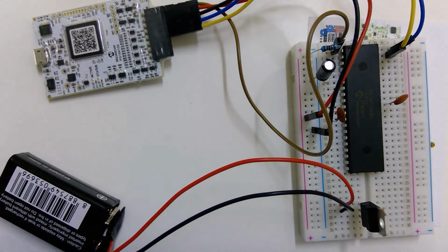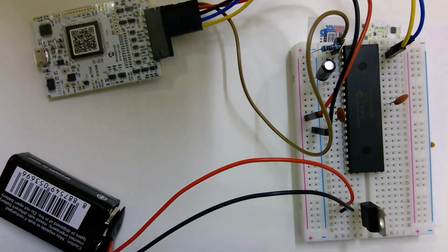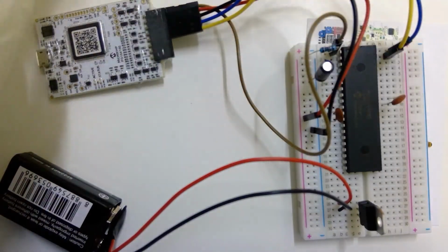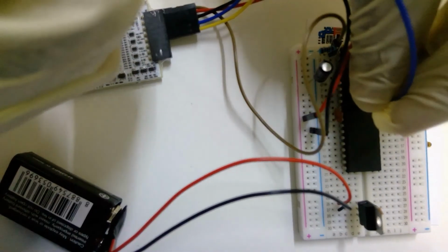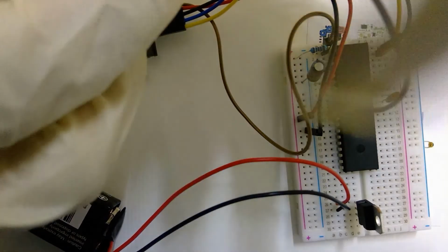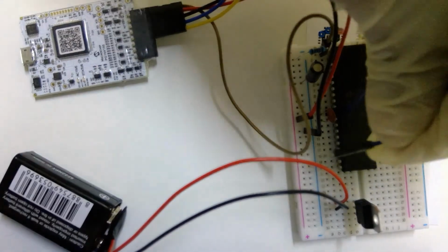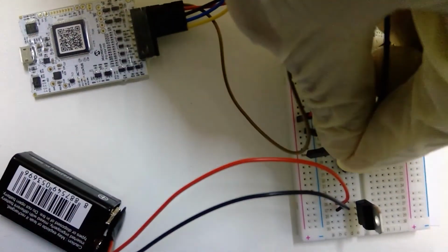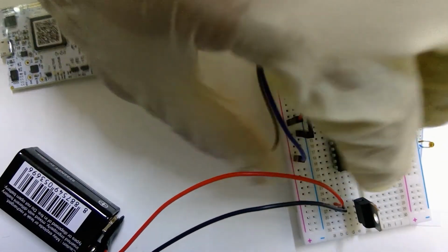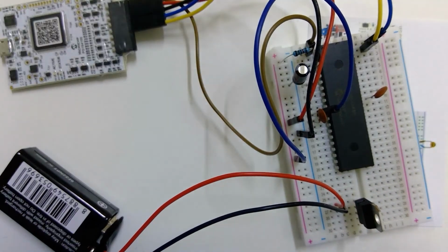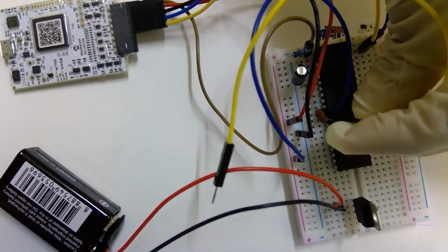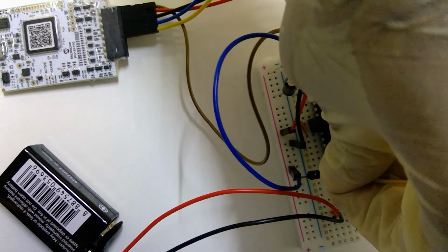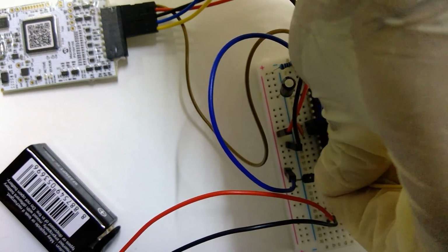So first let us connect the power and ground of the microcontroller with the power and ground power rail on the breadboard. So pin number 11 is the power, so we are connecting it here on the positive line, and pin number 12, which is ground, connected on the negative line.